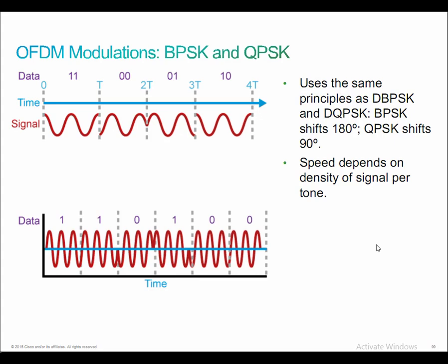So if you looked at an 802.11g spectrum, or you looked at an 802.11b spectrum, you have the same 11 or 13 channels, depending on what country you're in, and they have the same 5 megahertz gap between the 22 megahertz wide channels and so on. So the channel occupation and the frequency occupation is the same. Each tone is considered to be an independent carrier that actually bears data. So the OFDM mechanism ensures that the carriers do not interfere with one another.